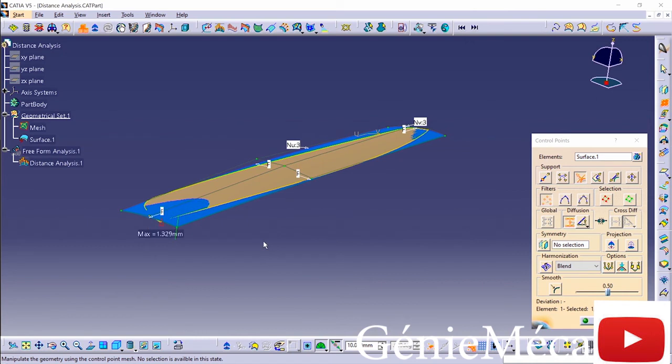It allows me to visualize where my deviations are. And again, those deviations might be necessary. You may have a poor quality scan, or maybe your curves have a lot of issues, and a larger amount of deviation may give you a smoother surface, but you may have to go back in there and tweak things to make sure you get the highlights flowing into the part or away from the part the way that the stylist wants.